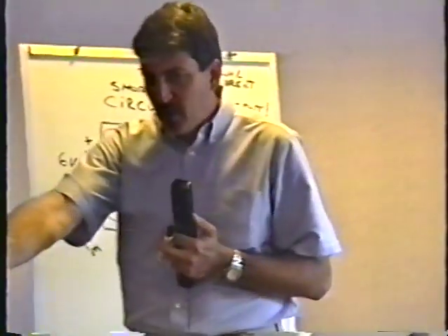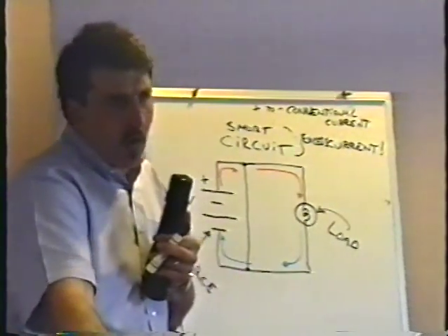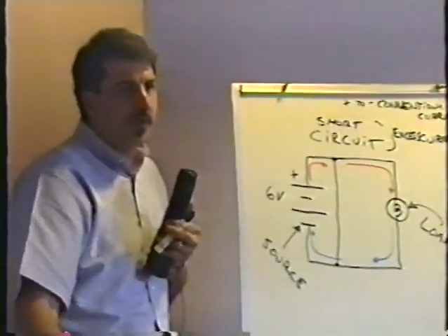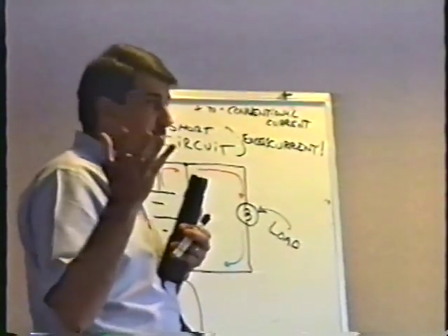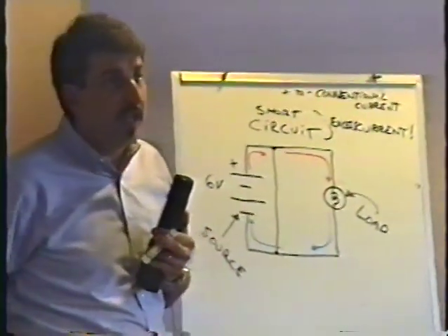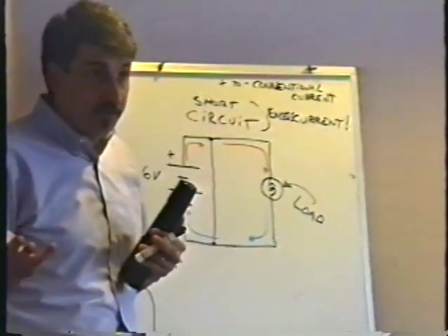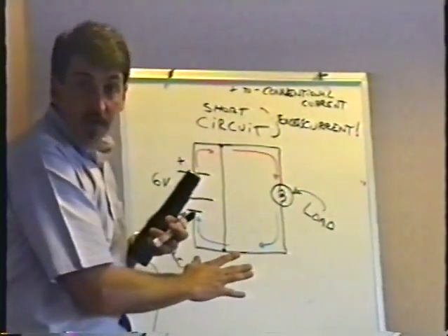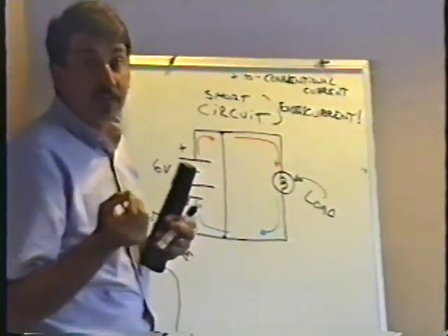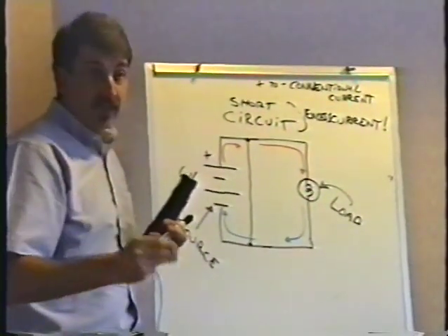Like you go to a location and they'll be pointing to the pinball and they'll go, hey, that number 5 bonus light doesn't light up, it must have a short in it. Well, bullshit, it's probably open, isn't it? The filament of the lamp is probably broken, it probably has an open circuit. So don't think that any failure is a short circuit. Some components, when they fail, do short circuit. I'll show you a part called a diode that always short circuits. When it fails, it's always a dead short.